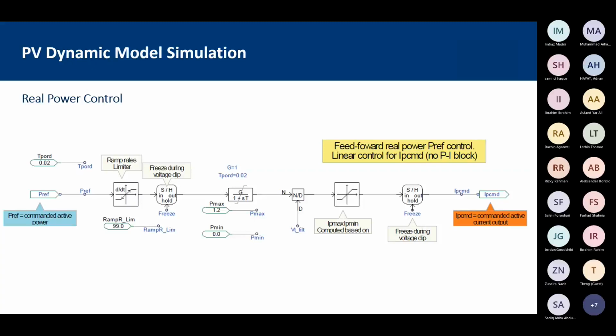Also, like a solar power system, it changes throughout the day. It means the irradiance from the sun changes throughout the day, and when there is a cloud cover for like 5 minutes, its output changes, and then it comes back to full output. So if we don't use those ramp rates, that's obviously a big fluctuation which the network has to bear.